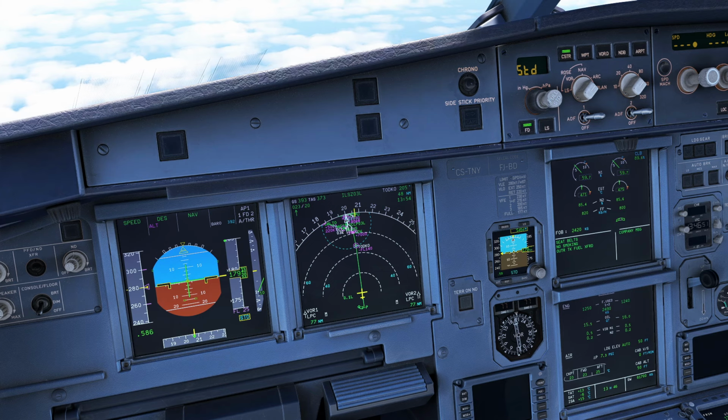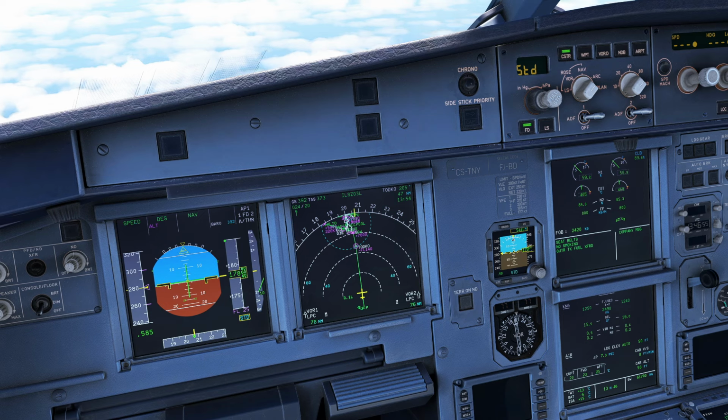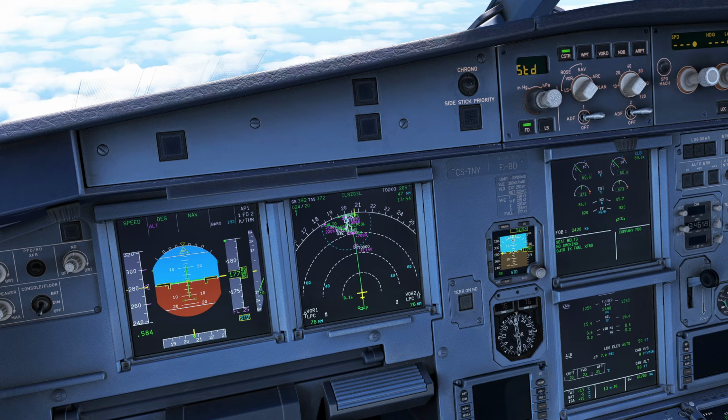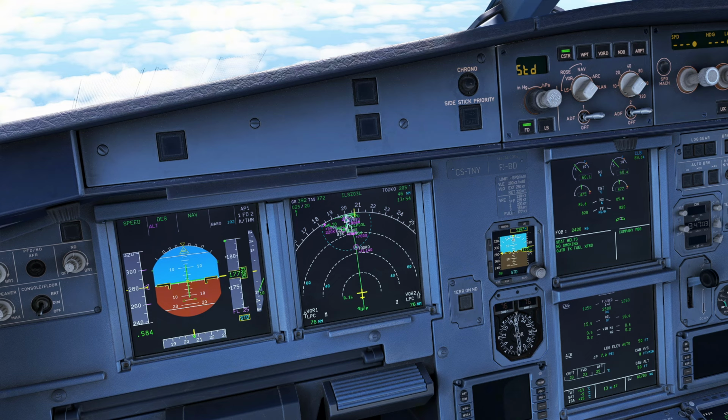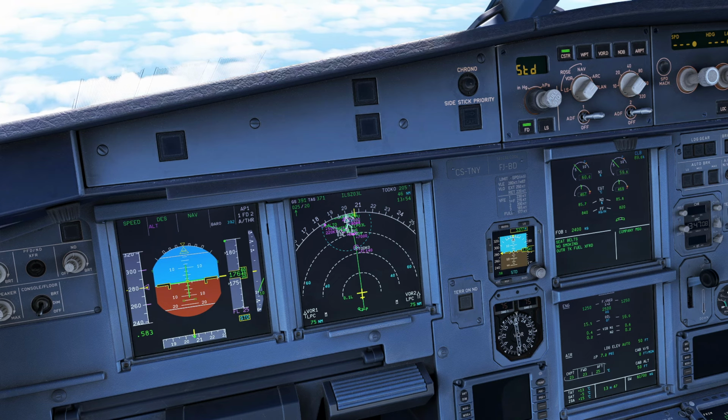For the configuration, decelerated approach means gradually configuring the aircraft throughout the descent, but for early stabilized approach, it will be done in an early stage of approach and fully configured before 1500 feet.